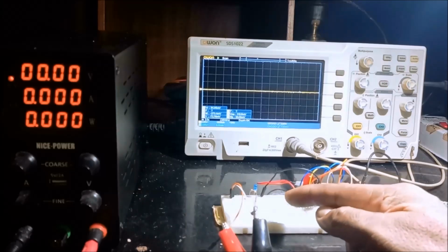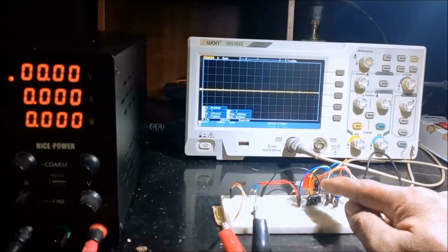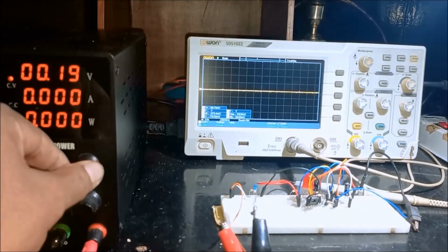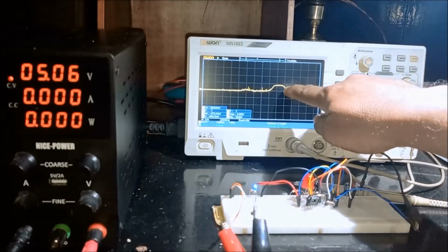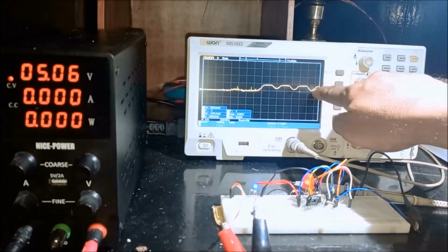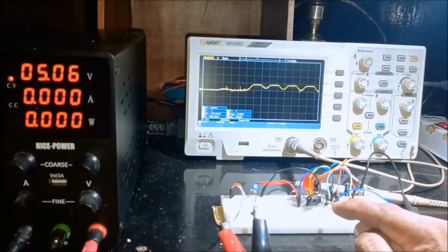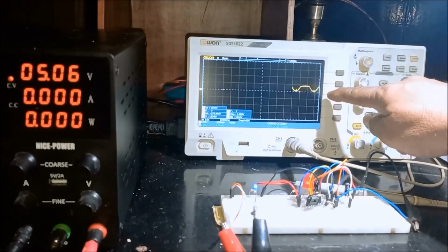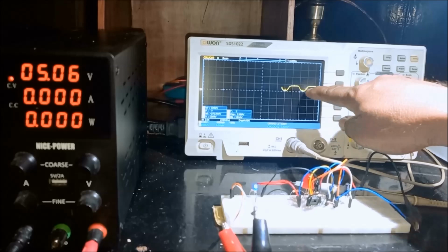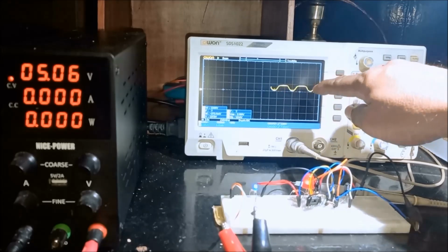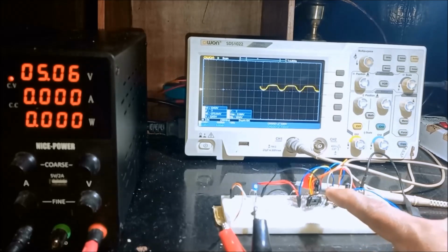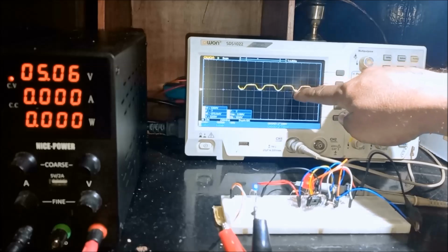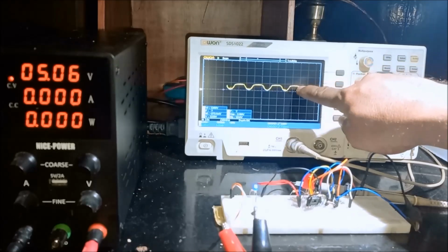We connected the oscilloscope across our output LED red. Then we're going to supply the voltage, 5 volts. So you can see here this is the waveform generated by the circuit. This is an oscillator. It looks like a clipper circuit with on and off, so that is the reason why the LED has a gradual turning, slowly turning on and then off.